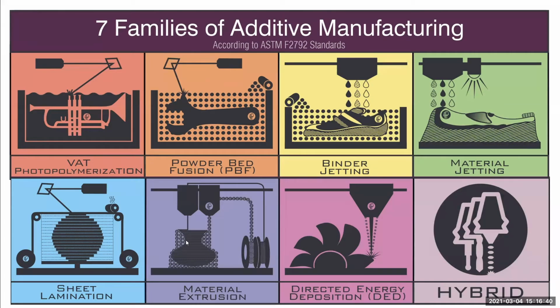So these like larger dots here, those are oftentimes when you see this sort of dual extrusion printhead action happening. A lot of times what's happening is that the primary print material is being supported by a dissolvable filament. So a lot of times what happens is that you can print a sort of hard, robust plastic in a plastic that dissolves in rubbing alcohol or in water or something like that.